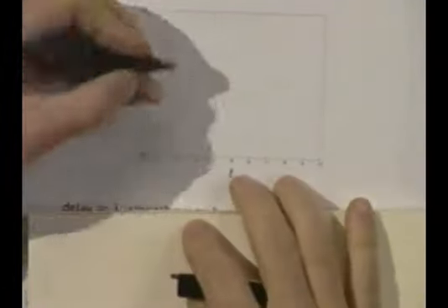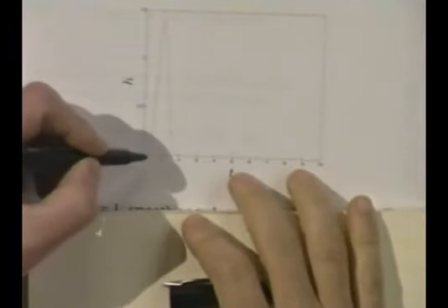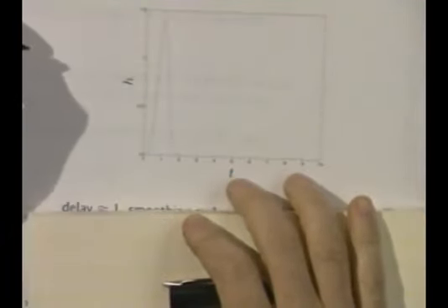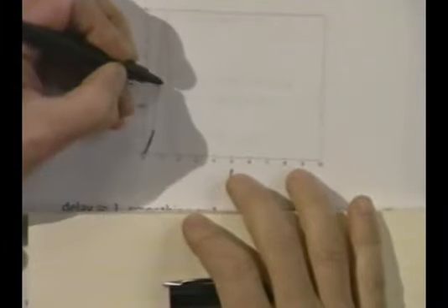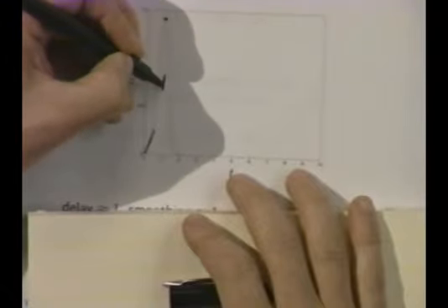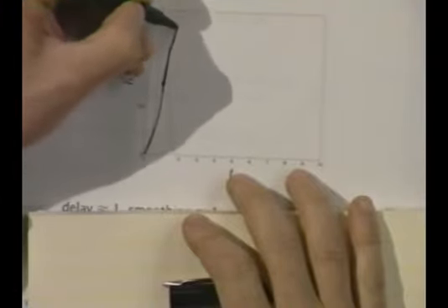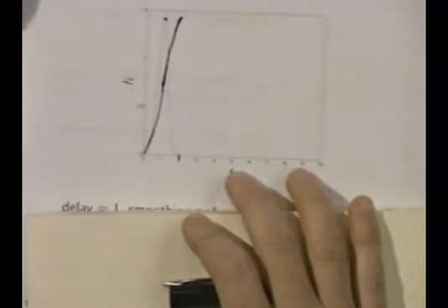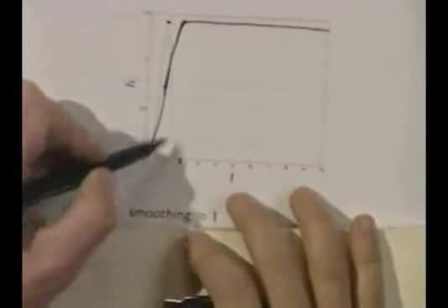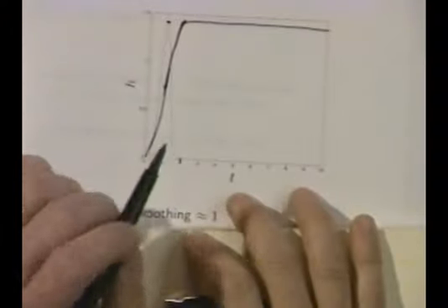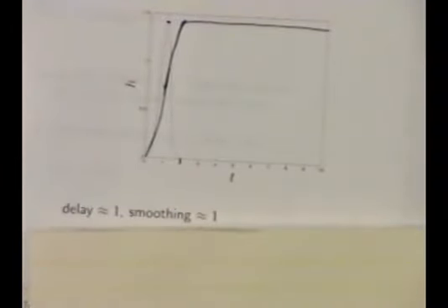Well, it's the running integral of this, and I'll draw it on another plot here. It looks like this. What's the running integral of this thing look like? Well, it goes up, right? It reaches its maximum slope right in the middle, like that. Then it slows down again, and when it reaches 2 seconds, it's converged, and the integral increases no more. So the step response looks like that. And what I've just drawn for you is what the output of that wire looks like when you walk up to it and apply a step in voltage.